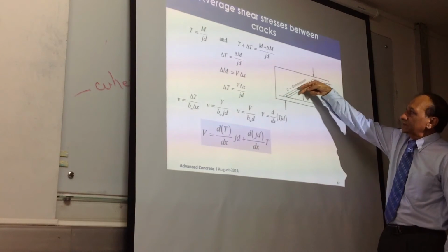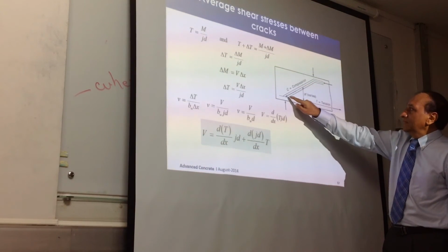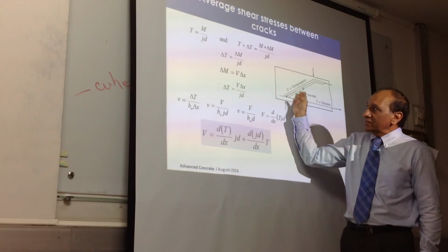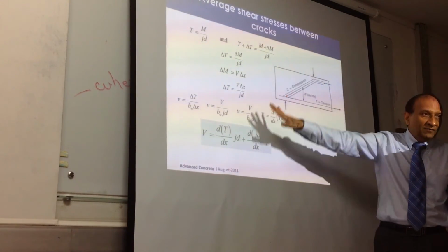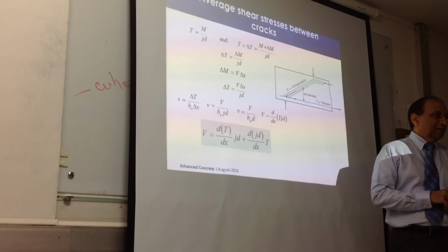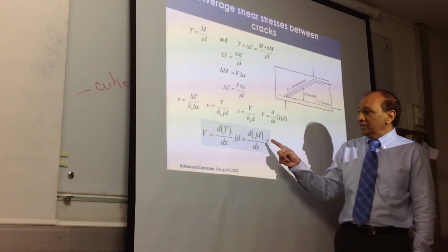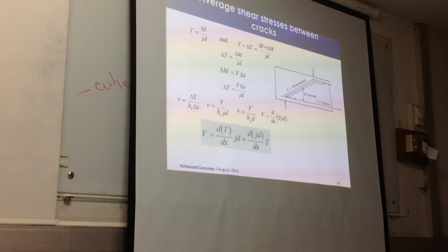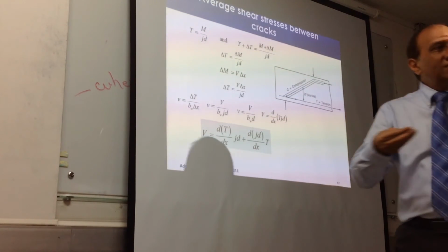So we have a compression here, we have a lever arm, we have a tension here, they form a couple, and based on that they can resist moment and shear together, and after that simplification we can come up with that equation. So what is interesting to see is D, the reinforcement that we provide also contributes to the shear design or shear strength, because it provides us, like I mentioned, the tension.